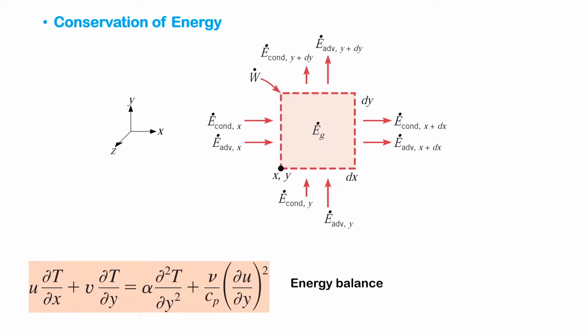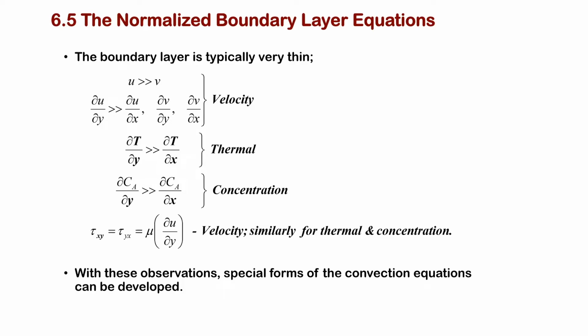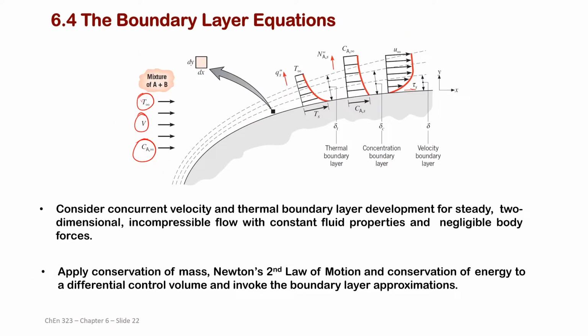And then you also need to think about conservation of energy. In this case, we need to think about internal energy coming into the system, internal energy leaving out of the system. Then you'll also have viscous dissipation that is going to cause some energy processes here. So this is the energy balance, when you couple fluid motion with internal energy balance.